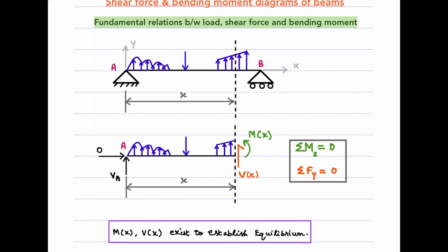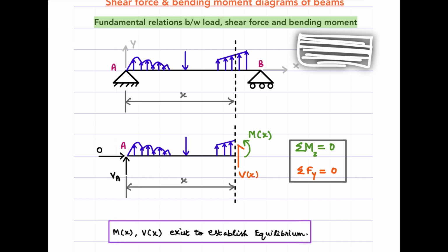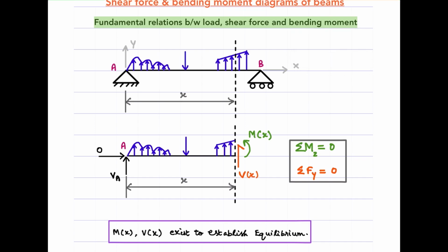What does that mean? That means the top fibers, if you take the same eraser and mark lines which are like this and do the experiment, we see that top lines will undergo a reduction in length, the bottom ones will undergo an increase in length. So if one typically assumes plane sections remain plane even after bending, we get a linear strain profile across the depth of the beam, right?